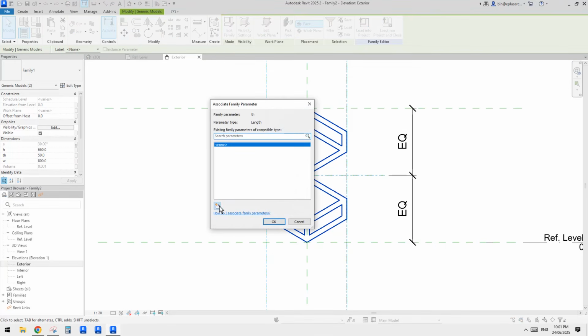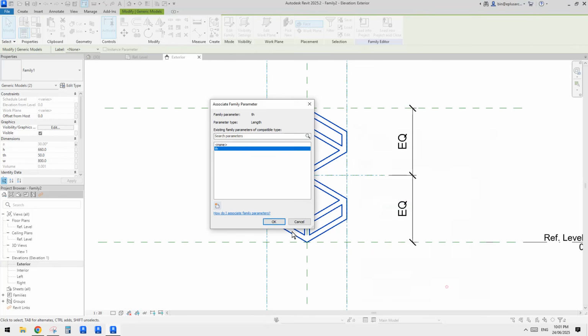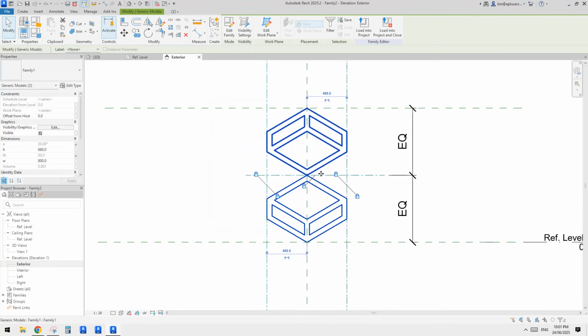So this one needs to be an instance because we want to control them depending on where these panels are, right? So for the bottom panel, we can increase the size of the opening, so we have a smaller opening. For the upper panels, we can just reduce that size, and then I think that's it.